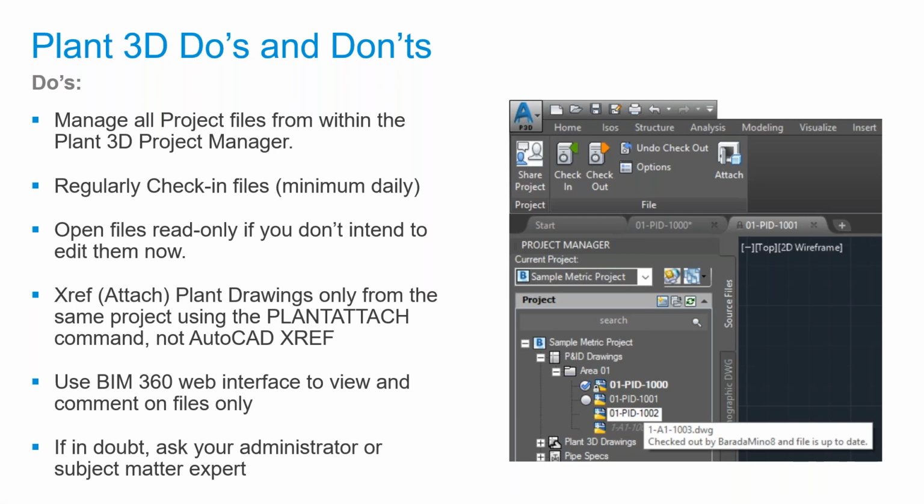So it doesn't get updated is what I see. Okay. You're best off, when you do an AutoCAD XREF command, it should definitely be something which is not in BIM 360. Like I was mentioning to one of the people that asked the question about the point cloud, you could have the point cloud on a local drive and XREF it in or attach the point cloud from that local drive, but it's recommended that you at least unload it before you save it back up to BIM 360 so that you're not having errors when it opens up again for somebody else.